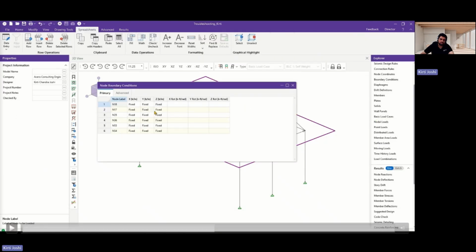And some of the reactions are related to the boundary conditions, because whatever load you have applied in a model, you are not matching it with the reactions calculated. We have provided a fixed condition, and fixed means it will just fix the model, but it will not calculate the reaction. So what we'll change in the boundary condition tab on the right-hand side is select all of the nodes and tell the software to calculate the reactions. So we'll just give a command of reactions.